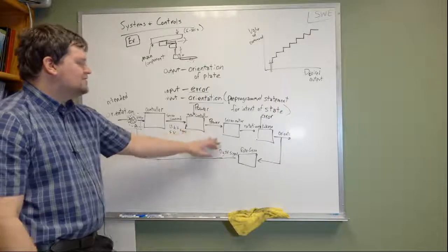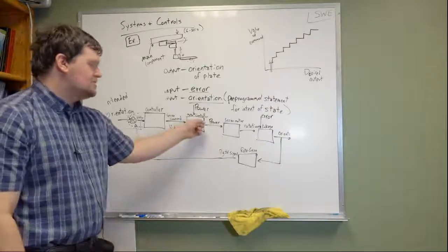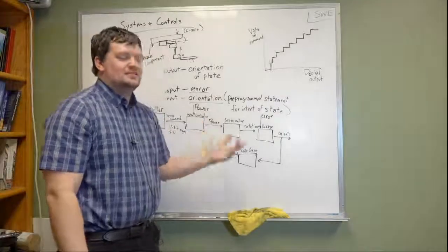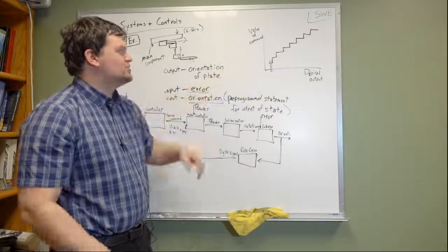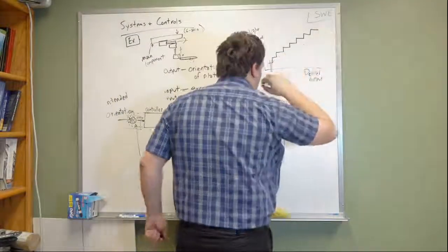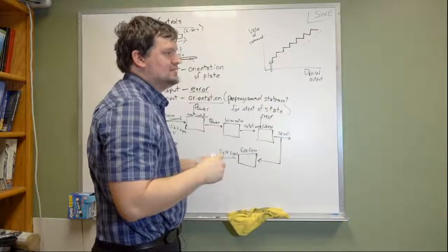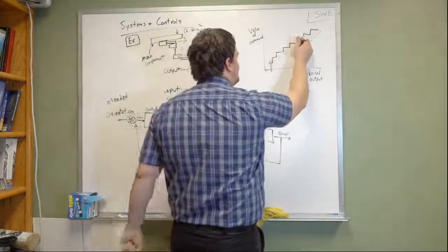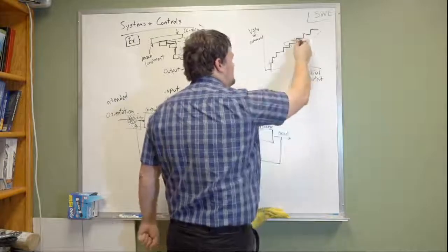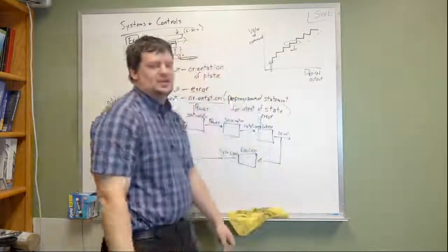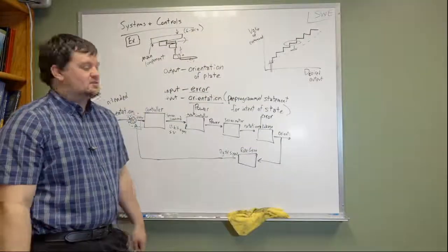Here there's an element of error that's associated once this has gone into the motor controller. There is a possibility that your motor controller is going to have a linear scale for what the output of that power actually is. So this may say, okay, I want this amount of power to be output, but in reality, if you go down here, there's only this amount of power that's being output. Okay, that's another source of error.